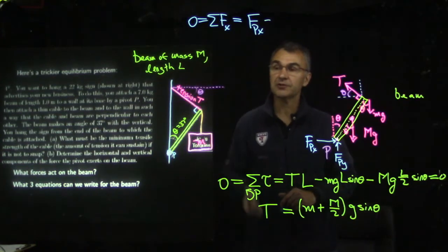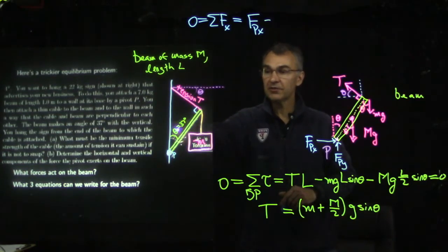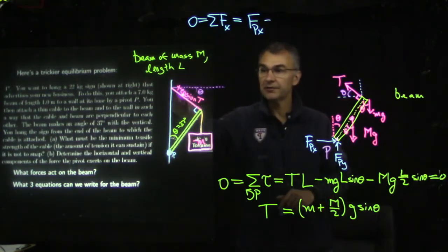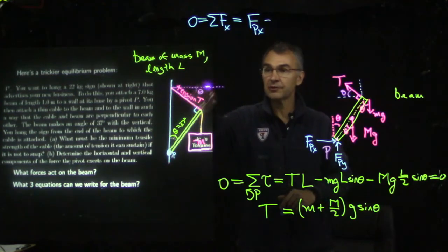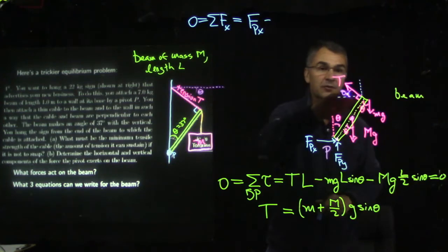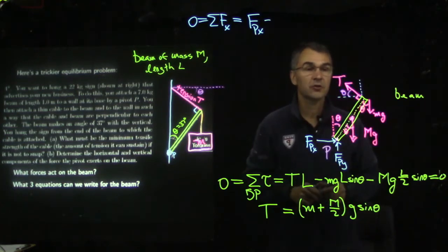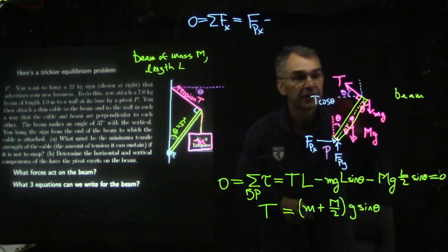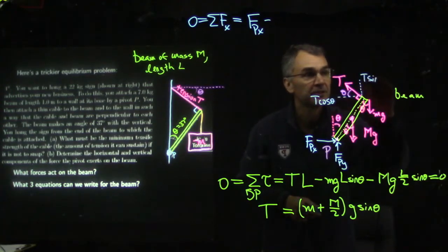respect to the horizontal. You can also see that if we made this angle theta very small, then we would make the cable almost horizontal. So that also seems to make sense. So I claim that this angle of the cable down from the horizontal is the same theta. Therefore, this angle on this diagram is theta. So the tension is at an angle theta from the horizontal. So the horizontal component would be T cosine theta, and the vertical component would be T sine theta.